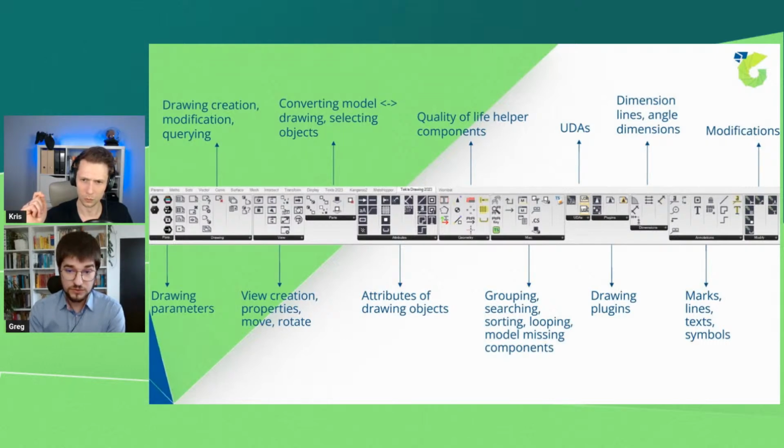You can also set some UDAs for the drawings, and it can be especially helpful when you would like to reiterate your drawing objects, so you get the information about which were created with the Drawing Link. You can insert the drawing plugins, and I think this is something not available in Tekla itself, because Tekla has a quite nice set of drawing plugins, but you have to insert them manually, and it's time-consuming. With the help of the Drawing Link, you can automate this process of inserting the plugins.